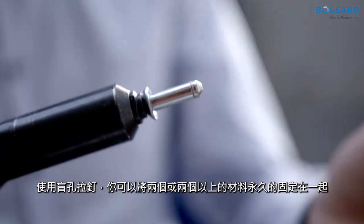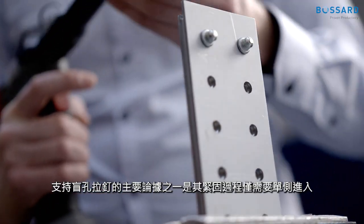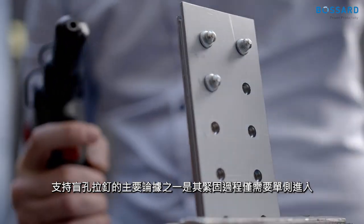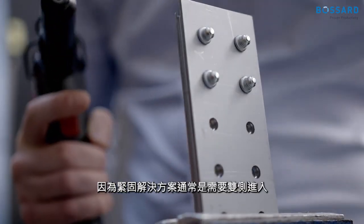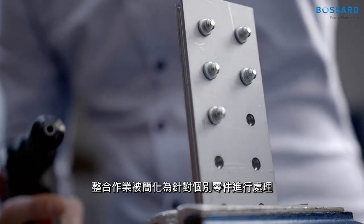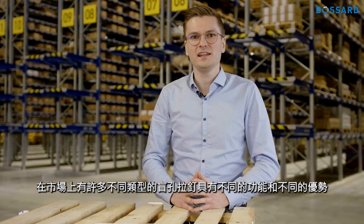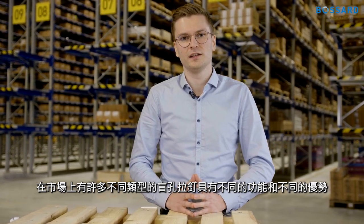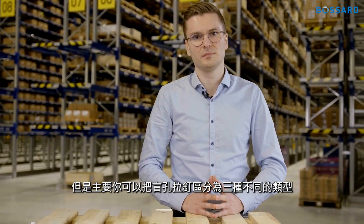With blind rivets, you are able to fasten 2 or more application materials permanently together. One of the main arguments in favor of blind rivets is that the process only requires one-sided access. This is a huge benefit because fastening solutions normally require 2-sided access. Their integration is reduced to work on individual parts or involves considerable setup costs. There are many different blind rivet types on the market, with different functions and different advantages. But mainly you can differentiate blind rivets into 3 different types.